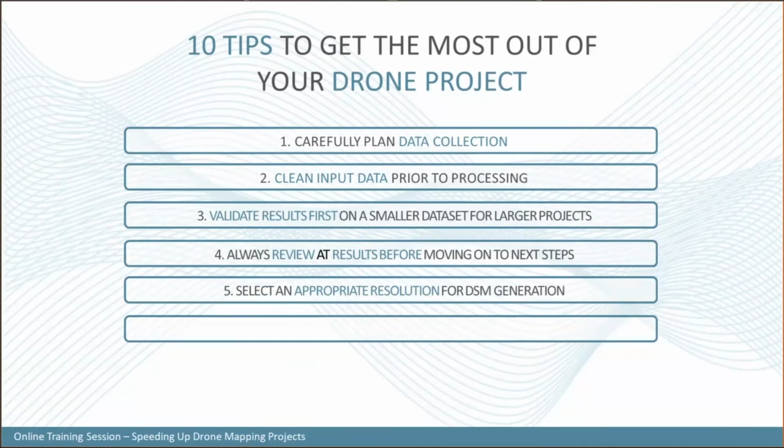You may want to lower that to 5 times, 6 times. For orthos and mosaic only, a good rule of thumb is between 5 to 10 times should be good enough for your accurate mosaic. However, if you required a highly dense surface model, well, now you'll need to have the appropriate resolution for your needs.